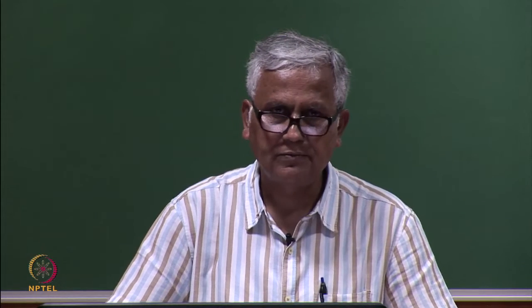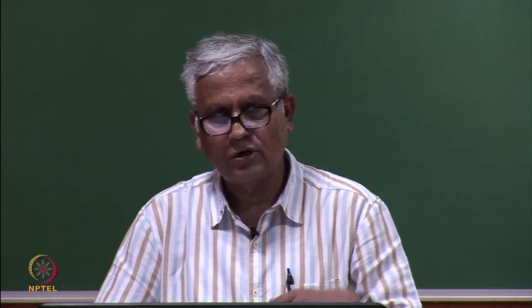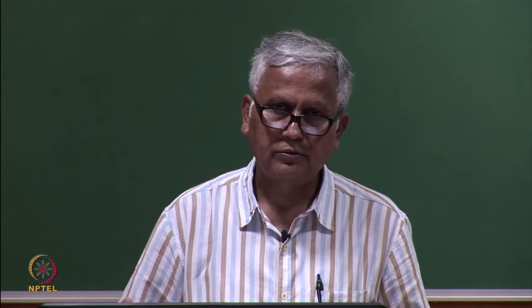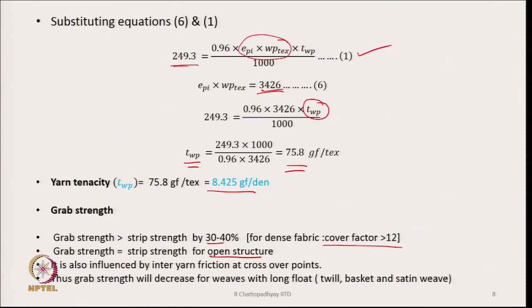Sometimes grab strength may be specified and therefore, you want to convert grab strength to strip strength to estimate the parameters. It is also influenced by the inter-yarn friction at crossover points. Thus, grab strength will decrease for weaves with long floats, twill, basket, satin. This is just general information which is stated here. So, therefore, yarn tenacity we could estimate right now.